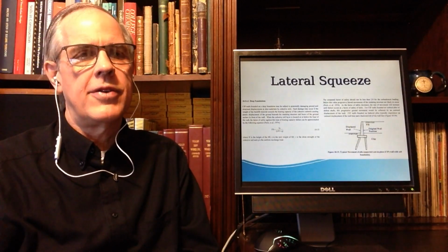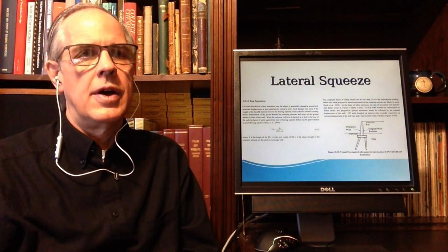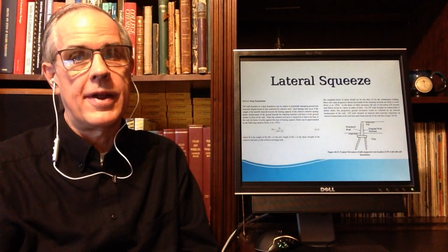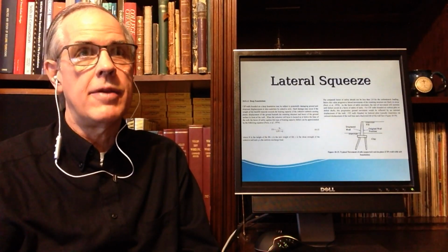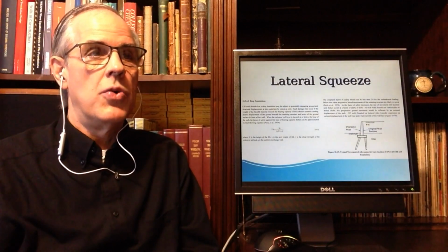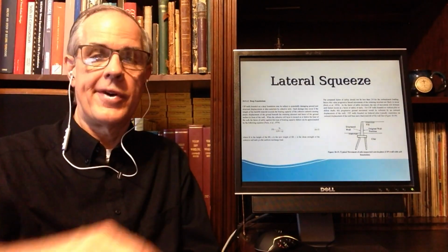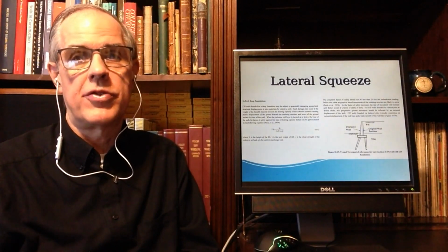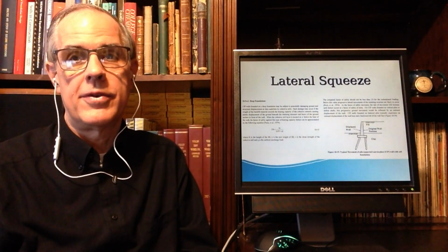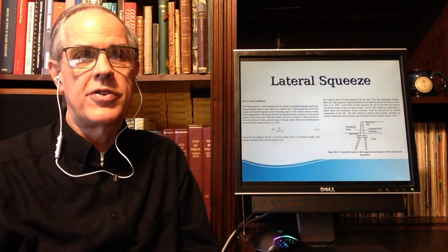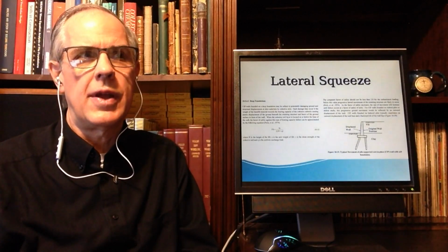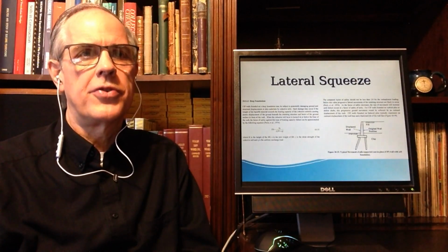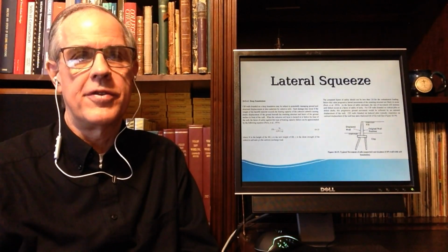And in some cases, with very soft soils, this doesn't always work the way it should. But in some cases, you would actually add, and we'll see this with sheet piling for sure, and maybe even with MSE walls, a uniform surcharge, which will actually up the lateral pressure, where we can take lateral squeeze into account. But with very soft soils, very frequently you get lateral squeeze, because in soft soils you get fairly substantial volume.